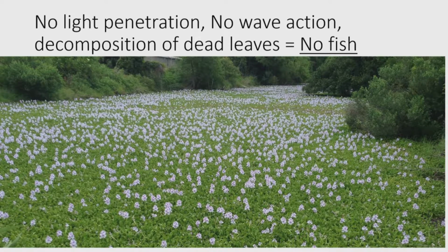So why is it a problem? Well, the way these aquatic systems work is you need native plants in that system. Sunlight penetrates the water column, photosynthesis occurs, and it releases oxygen into the water to support all the life. When you completely cover over the surface, not only does photosynthesis cease from plants as well as your algae and other small floating plants, you end up with no oxygen being produced and actually oxygen being consumed as decay occurs in that system.